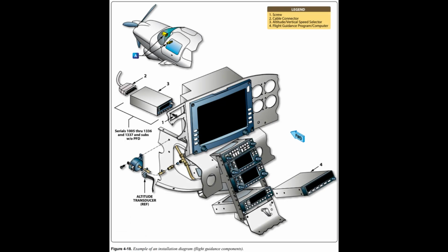Diagrams. A diagram may be defined as a graphic representation of an assembly or system, indicating the various parts and expressing the methods or principles of operation. There are many types of diagrams, however, those that the aviation mechanic is concerned with during the performance of their job may be grouped into four classes or types: installation, schematic, block, and wiring diagrams.